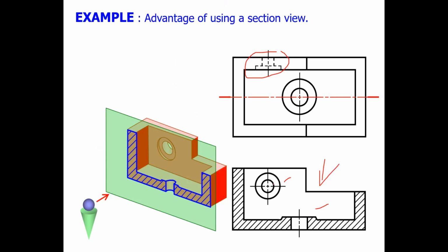Be careful, that's a rule of sectioning. When you do the view with section lines, at the back there, sometimes the other half has another hidden structure, but do not put hidden lines. Understand, that's the idea: to facilitate dimensioning, to make a simpler view, to eliminate hidden lines. I'm only talking about the front view, not the top view. Don't misunderstand. The top view still remains ordinary orthographic, but we have the cutting plane. Clear? Understand, class? Good.